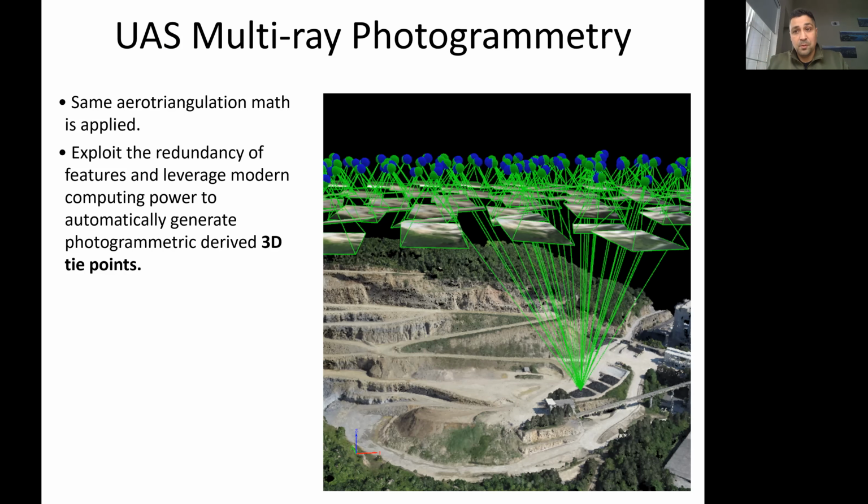The point I'm trying to make is that you have to have, number one, solid key points. Number two, a sufficient amount of automatic tie points that came from those key points, that were matched from those key points. And three, if you have those first two things, the rest of the build out during the processing will be in a much more solid state.